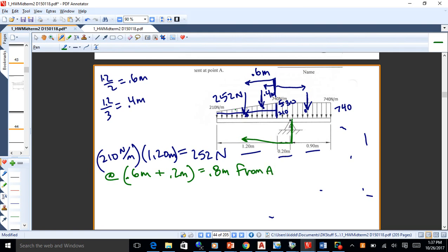Okay. So you get those initial measurements in blue on the top there, the 0.4, the 0.6, and then the what, 0.55 I think it is. Those are measured from that boundary between the figures, because that's kind of the natural place to measure those. But we're taking the resultant at A, so we basically have to shift all those measurements by 0.2 meters over to get to A from that boundary. That's the idea.